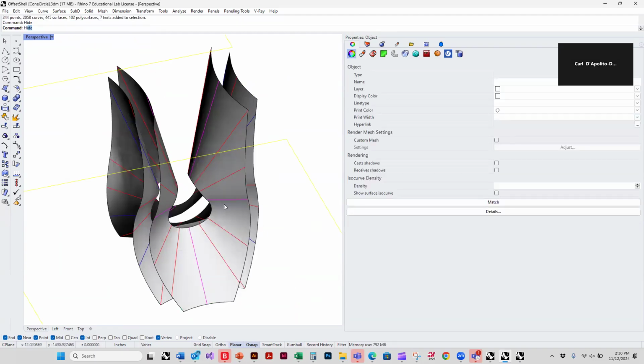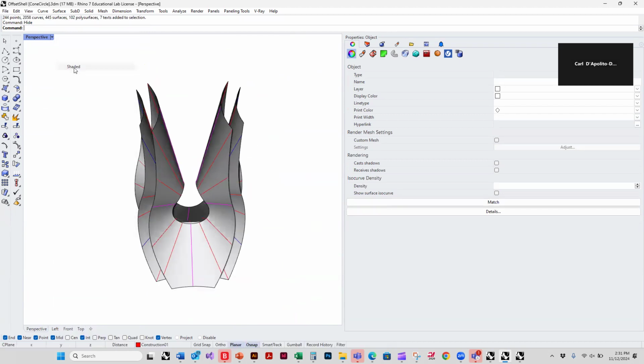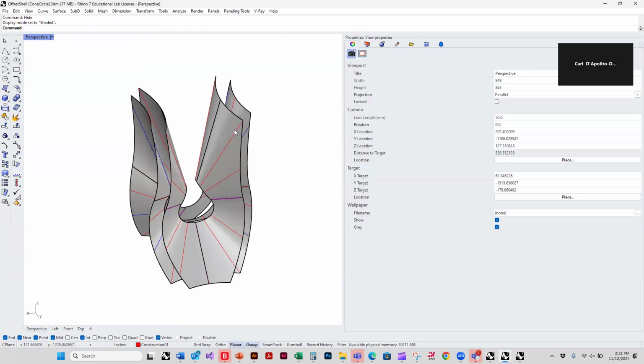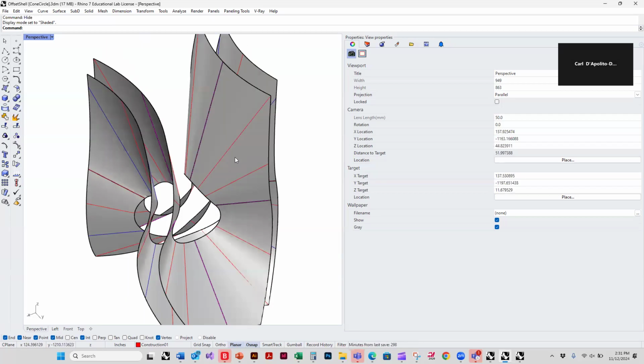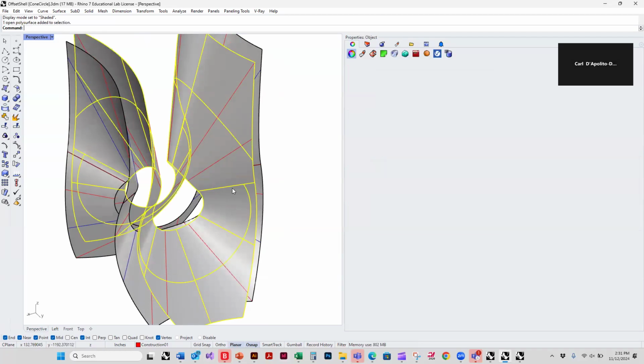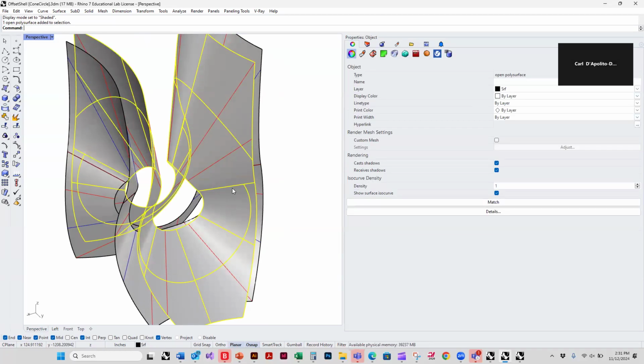And this is a developable surface. So going back to what I said at the beginning, there is no reason this needs to be subdivided at all. However, if you unroll it, it'll overlap itself. And also, it was too big for the sheet of wood and aluminum that I had, which is a very common problem. So I just looked at this top surface and chose lines that I wanted to divide it down into.